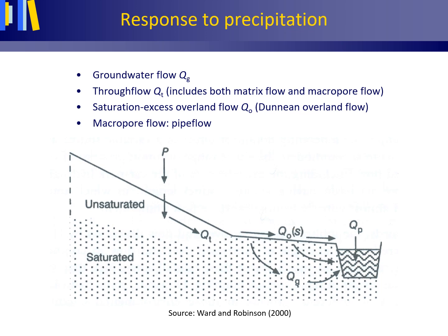As the natural soil pipe's diameter of a mole or vole burrow is in the order of 1 to 2 centimeter, the matrix threshold suction must be almost 0 centimeter, meaning that the surrounding matrix must be near saturated. Similarly, artificial drainage pipes, for instance used to drain cultivated land, are only effective when the soil matrix is near saturated or when the water table rises to the level of the drainage pipe.